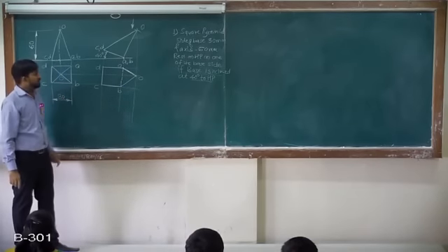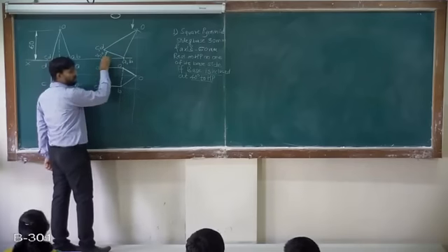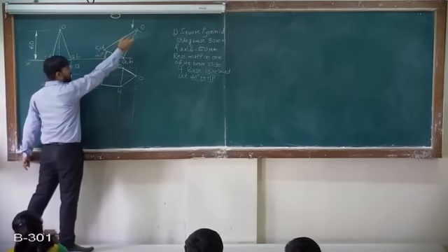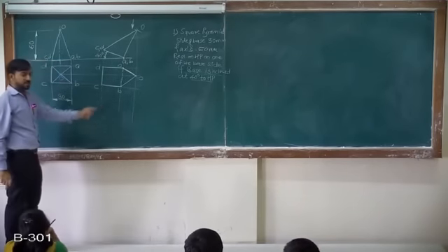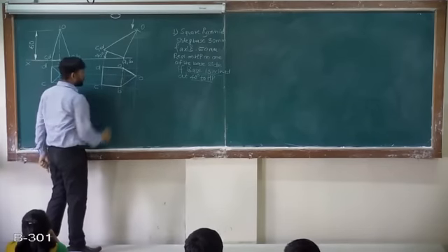Got it? So a very simple case, when the angle made by base is given, I need to take the 40 angle, take this distance, accordingly locate O, take a projection and draw this view as the second stage top view.